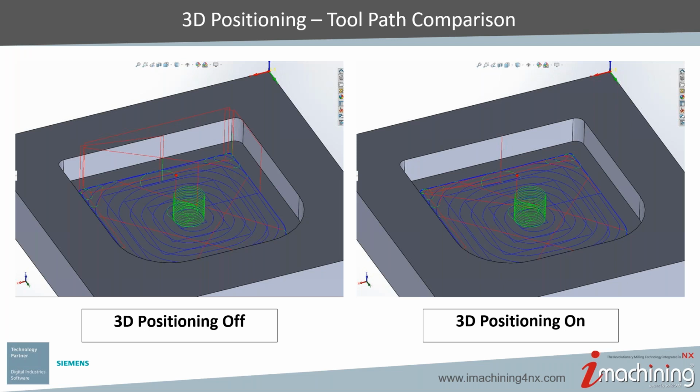As a machinist, would I say that this is going to have a faster cycle time? Maybe a little bit, because as we know, when the machine is rapiding, it machines in exact stop mode. So every time you rapid, it does take time to go up and down. From my side, I like it more as an operator. Every time the tool rapids up and over and down, it's that position when you're running the machine, especially in the setup, when you're first setting up the part and running through before you have a whole part running, where you're a little concerned.